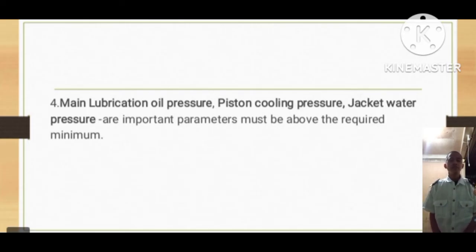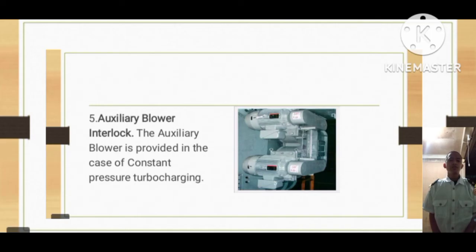Next, the auxiliary blowers. Auxiliary blowers are part of ship engines, and usually they are assembled in pairs. Both auxiliary blowers start operation before starting the ship engine and provide adequate pressure of flushing air for a safe startup of the ship engine. The air side cannot be isolated as the auxiliary blower takes its suction via the air filter. Thus, air isolation of the turbocharger relies on the non-return valve fitted at the inlet to the scavenge air manifold.